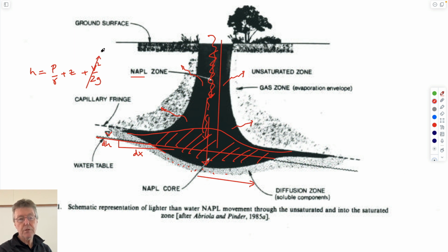Velocities are inconsequential. We throw those away, and we worry about what the change in hydraulic head is. It's basically given by the slope of the surface, and so this will allow us to define the velocity. You've seen Darcy's law, right, in your past. I'll write it in terms of hydraulic conductivity times the head gradient. So if we know what this head gradient is from this slope, we know that this is finite. If we know that this is a finite value, then this velocity is a value that we can calculate.